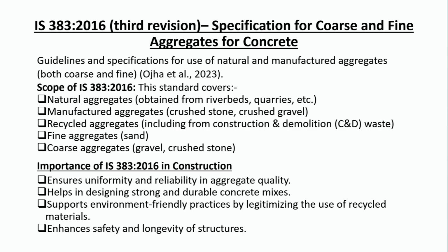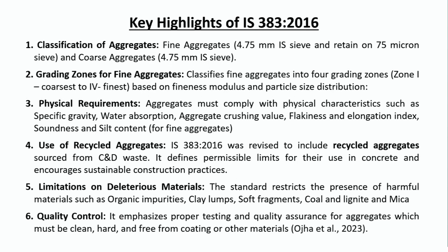The importance of this standard in construction: it ensures uniformity and reliability in aggregate quality, helps in designing strong and durable concrete mixes, supports environment-friendly practices by legitimizing the use of recycled material, and enhances safety and longevity of structures. Key highlights of the Indian standard: first is classification of aggregates, second is grading zones for fine aggregates, next is physical requirements, next is use of recycled aggregate, thereby limitation on deleterious material, and then quality control.